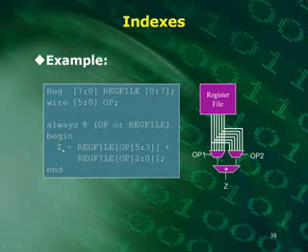And the output is based upon this function. I said reg_file of the upper 3 bits of op. If I've got 3 bits, I can select one of 8 locations, and I have 8 locations in this reg_file.